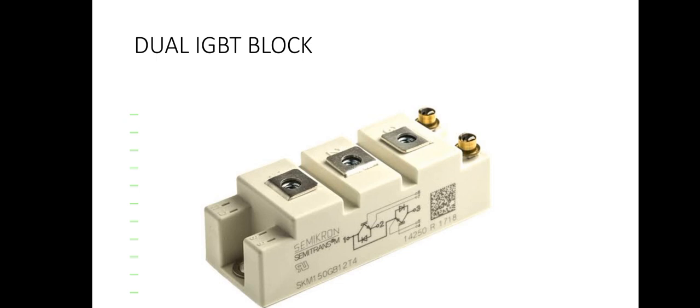So this is a typical image of the IGBT block. These are mostly recommended for high voltage inverters. Maybe you don't want to do much soldering and assembling, you can use this IGBT. They are very expensive, but they last very long and take time before they get damaged. Most times, if you see these IGBTs bridging, it is just in sleep mode. Once you disconnect it and keep it for 24 to 48 hours, it will recover and you can continue using it. That is the advantage of this particular device.